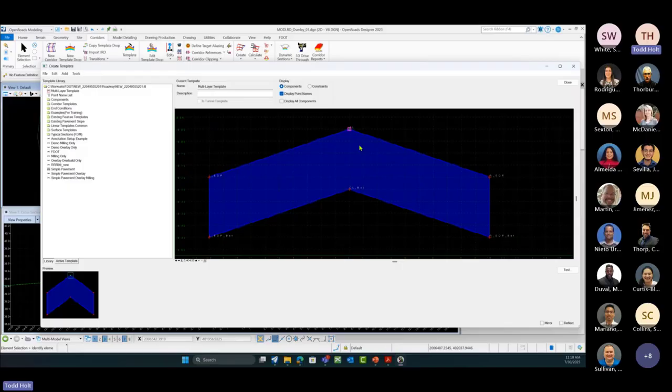All right, so now we're going to set up a premium overlay component. And the example that we have, we're going to set that to the component depth. We're going to set it to 4 inches. Or we can set it to, maybe it's a 2-inch premium. That's good. And then we can set another one to 2 inches or create an economical that we fill in that area on there.